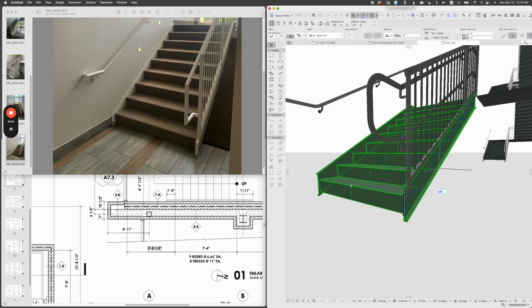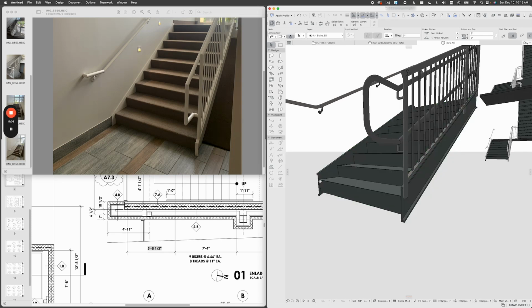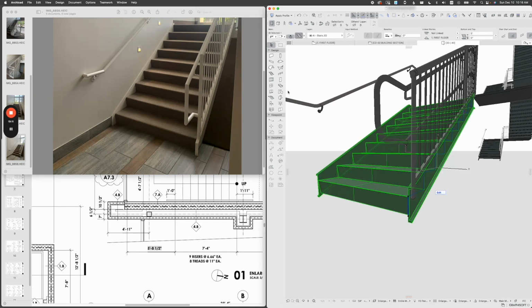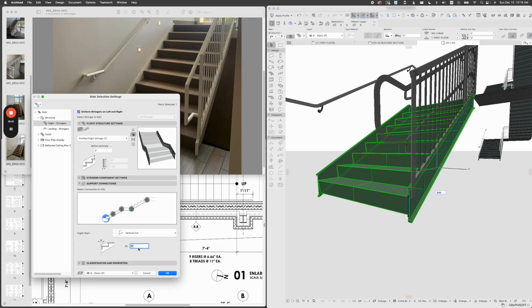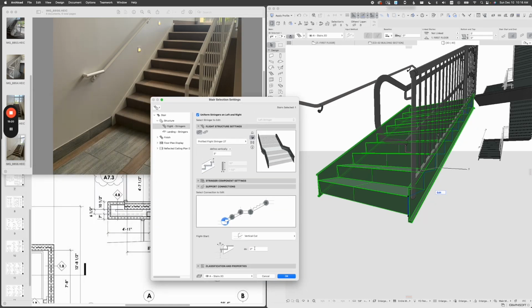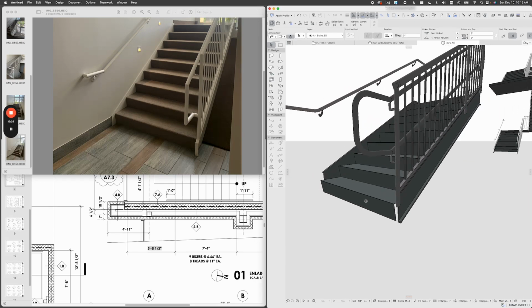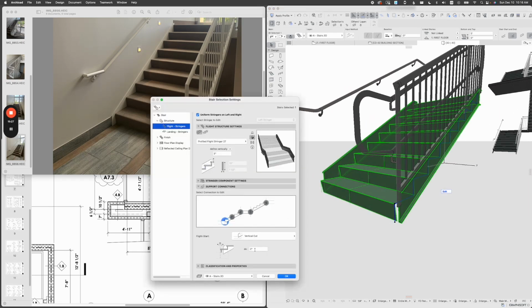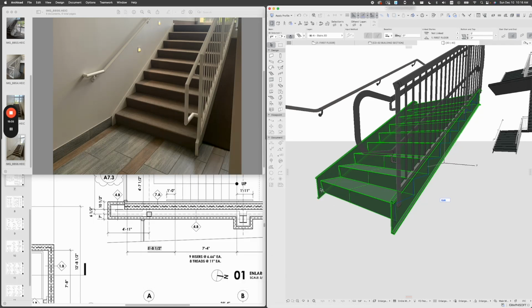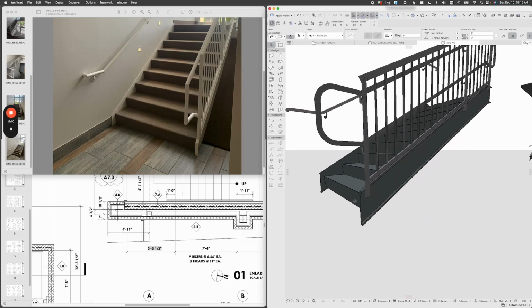Looks like we still have some offset. It's not really exactly like this. So let's go back again and just set some distance here. We can set this to 2 inches. Well, I already tried that, and if you just leave a positive number here, it actually goes back. So instead of a positive number, you just do a negative number. You say minus 2 inches, and that way it pushes these stringers in the opposite direction.